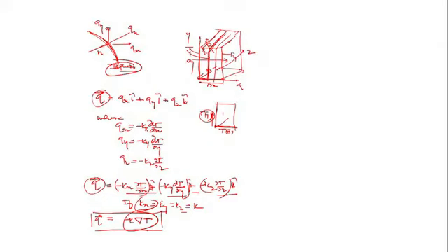But what is the definition? Thermal conductivity is equal to the rate of heat transfer through a material of unit thickness, unit area and unit temperature drop. Yes or no? K is equal to Q if area is unity, delta T is unity and delta X is unity.